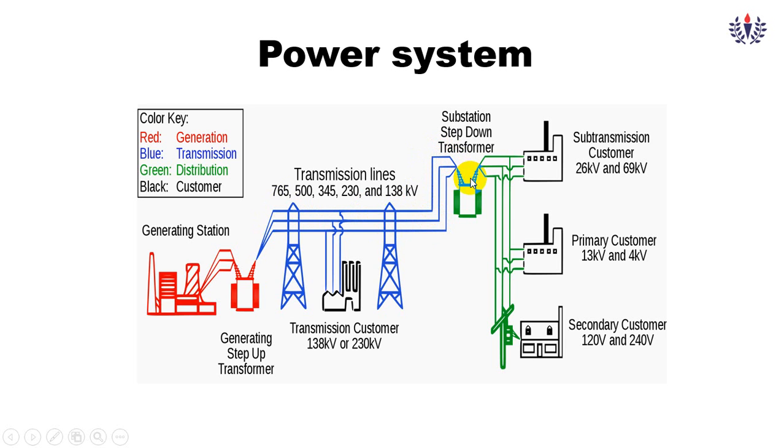Once again it comes to one more transformer, where the step down process happens. We might have studied the transformer in module 3; the same is utilized here. So here you can see the step down, which may be around 120 kV or 240 kV according to our use. Here 138 kV is stepped down to 28 or 33 or 66 kV once again, and it is given to the distribution. Here you can see the distribution in the green color.